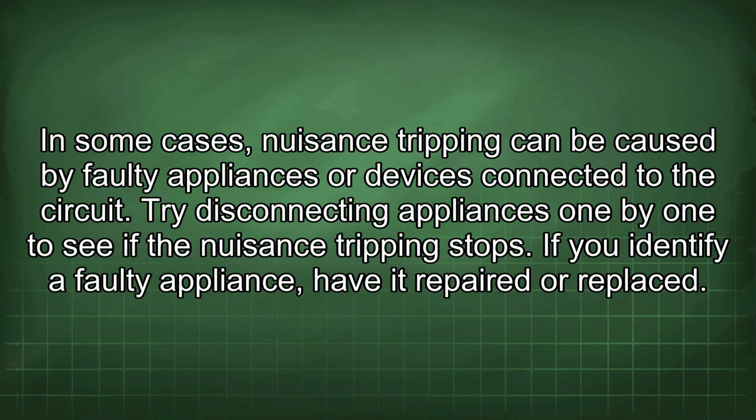In some cases, nuisance tripping can be caused by faulty appliances or devices connected to the circuit. Try disconnecting appliances one by one to see if the nuisance tripping stops. If you identify a faulty appliance, have it repaired or replaced.